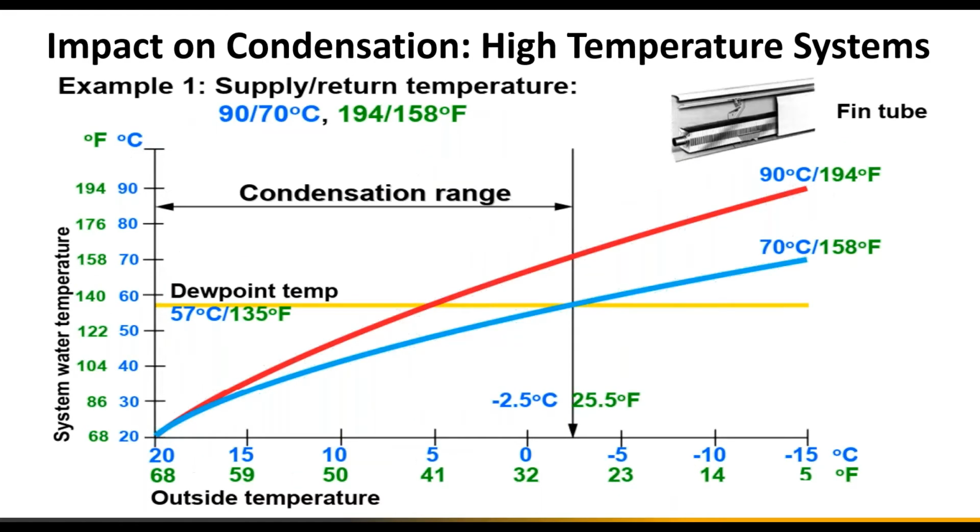Moving on to the next slide, this is your typical high temperature curve. You may have an existing apartment building, new boilers need to be put in. All we're looking to do is take the old boilers out and put high efficiency boilers in. We still need to supply 180, 190 on design day to the system, and at about a 160 return. And this is based on, say, design conditions being 10 to 5 degrees Fahrenheit.